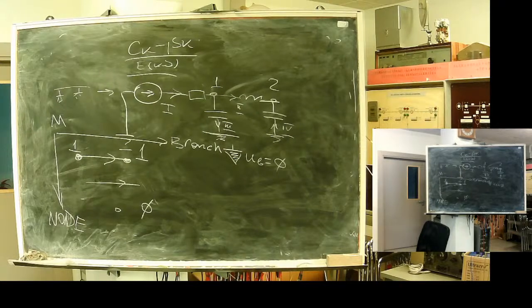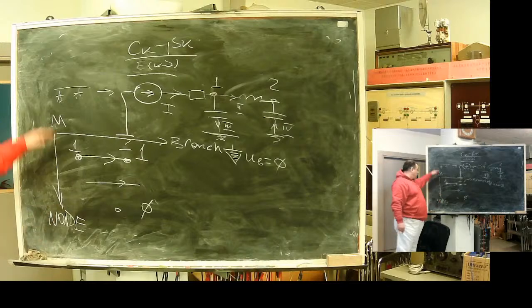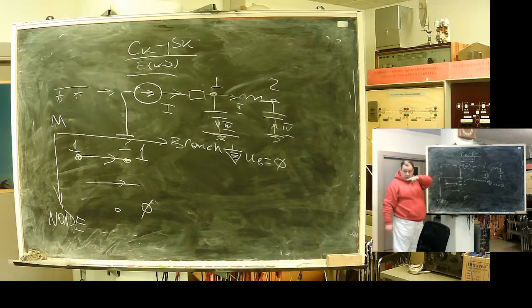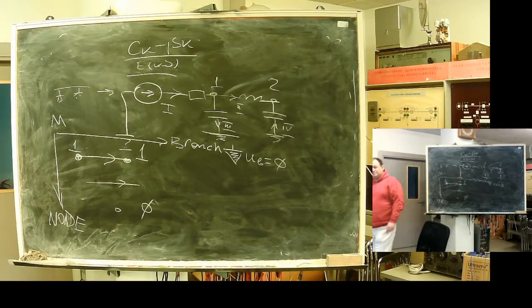Professor, what is this called again? The branch versus node? Node, it's not numbering. Row numbers corresponds to number of node, and column number to the number of branch. And the flows in minus one. Flows in, -1, flows out, 1. No connection, 0.